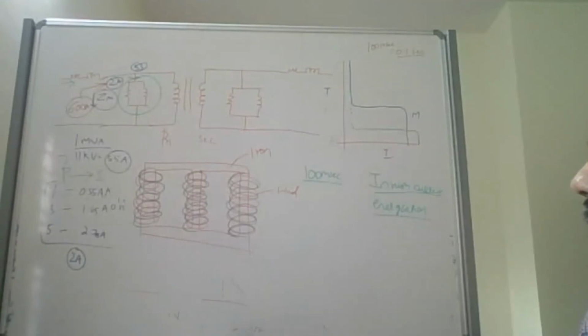That's why we are having such a high magnetization, right? Not short circuit completely. You are correct, but not complete short circuit because then it will become infinite current. Instead of short circuit, it will be very, very less impedance. That is what is causing such a high inrush of about 10 times the current.